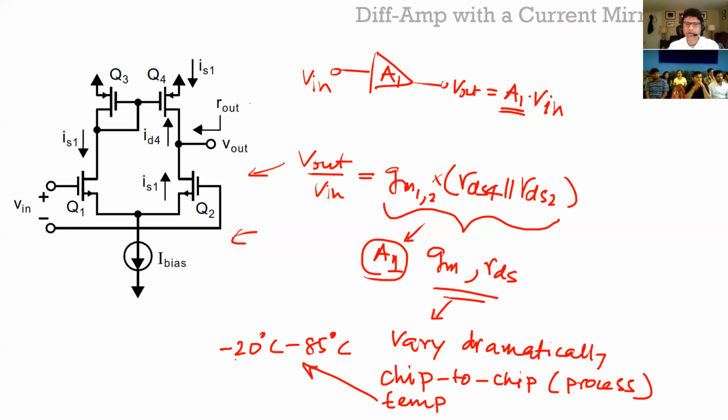So for example, all the chips in your cell phones, which you're holding in your hand, are actually spec'd at this. In other words, every chip inside your cell phone has to function over this temperature range. Now you might ask, I never live in a place which is 85 degrees centigrade. That's the junction temperature. So let's say you have a hot summer where it is 40 degrees C, then you can have another 45 degrees C within the junction, because of what's called the thermal resistance inside a chip.